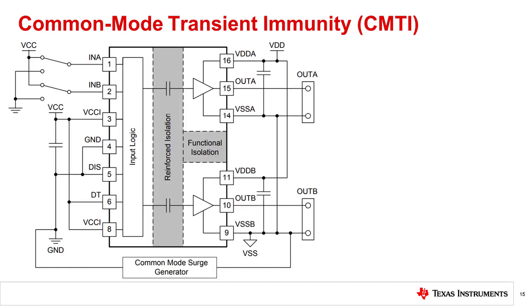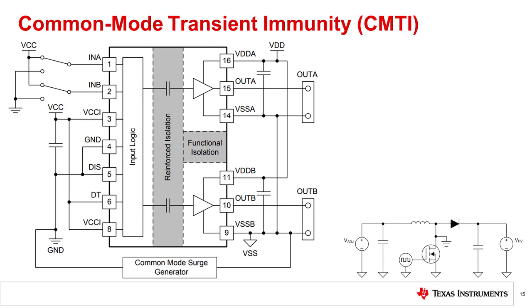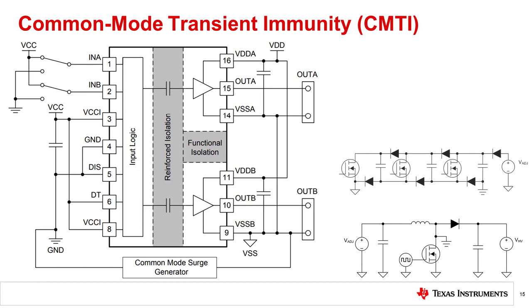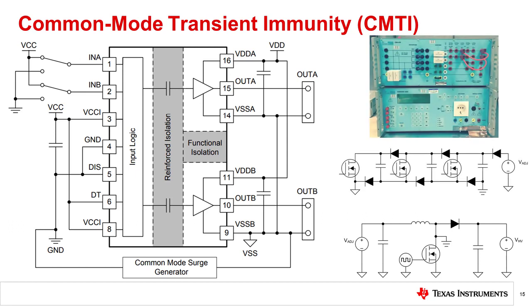Measurement of common mode transient immunity can be complicated. First, an adjustable transient generator must be designed or selected. Examples include the switch node of a switching converter, a transistor-based Marx generator, or some other electrical fast transient generator. Second, the transient must be measured.